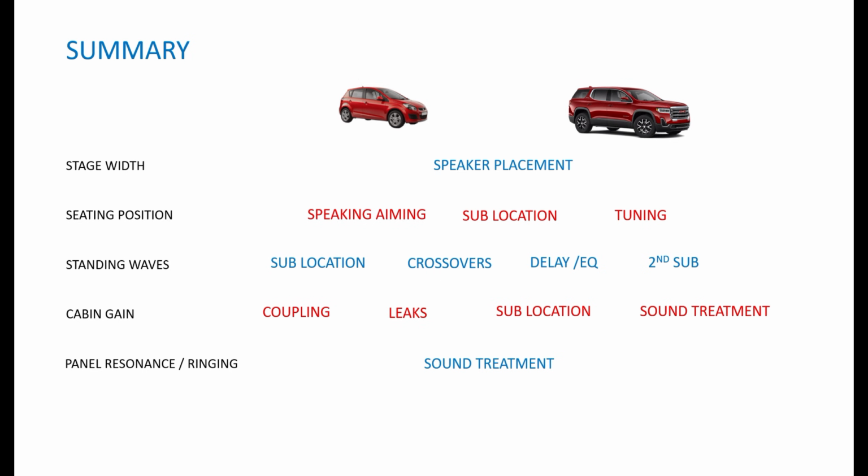Cabin gain, trying to get that ultra low boost, improving coupling between the air mass from the cabin and where your sub is located, trying to minimize air leaks, where you place your sub and trying to get some boundary loading, using sound treatment to stop rattles and things that give you much cleaner bass, are all solutions to try to improve cabin gain. And finally, panel resonance and ringing. The answer there is sound treatment. So yeah, a lot to take in.